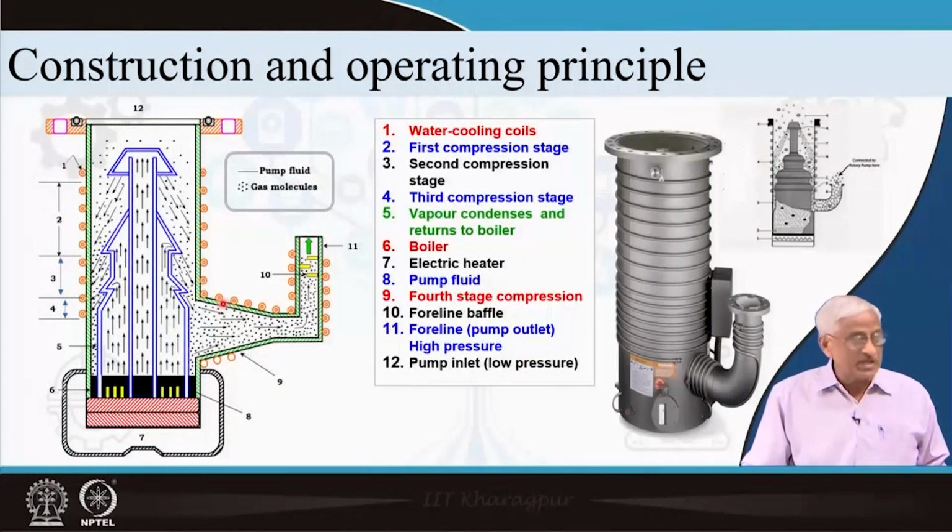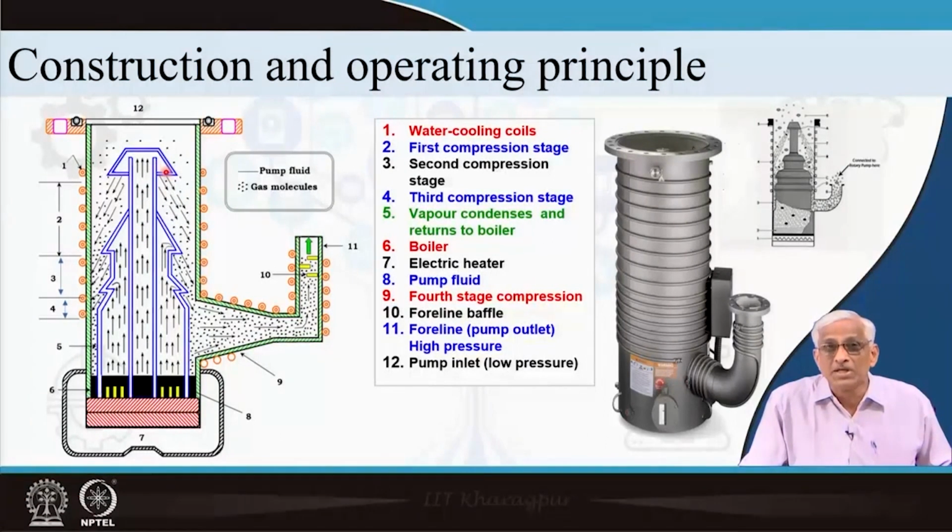In a few sentences: the oil molecules are heated in a pre-evacuated cylindrical container. They go through the top of the chimney, come out like a supersonic jet, get condensed by a water cooling arrangement, and come down.